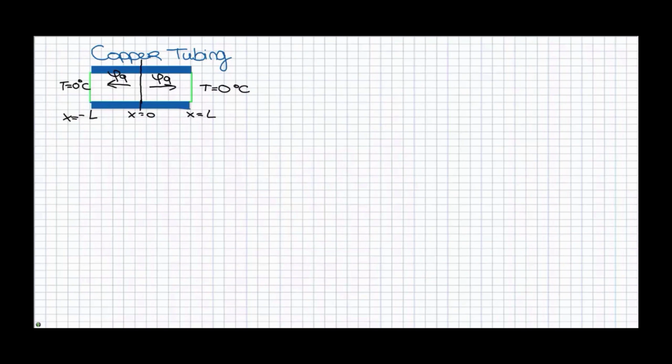In the situation described by the exercise, heat is produced in a tube. And we would like to investigate in this question the temperature profile in the tube wall due to this heat production. For a first rough estimation, we assume the tube to be a flat plate, which you can see in the sketch. The length of the tube is 0.5 meters, so half of the tube is 0.25 meters.